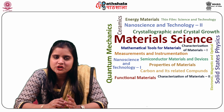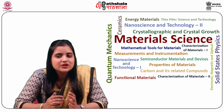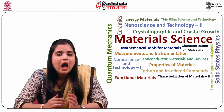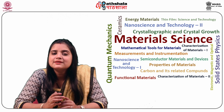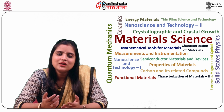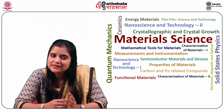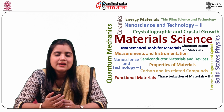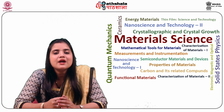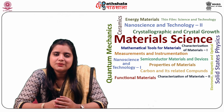In such a situation, it is customary to represent the dielectric data in terms of epsilon prime of omega and AC conductivity sigma AC in low mobility, or I can say insulating materials. The AC conductivity sigma AC can be expressed as sigma AC is equal to capital A into omega raised to power S, where capital A and S are the parameters.